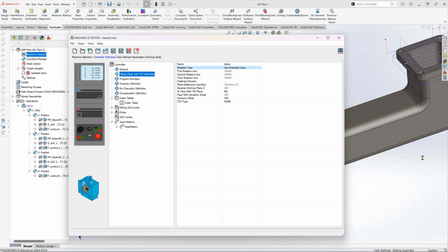We do have functionality that we are implementing in SolidCAM with hidden heads in machine simulation, so if you have a lot of different types of heads on your machine, we can support it. We can define the head exchange and show it in simulation, and of course get the G-code. But it's not supported in ToolKit.